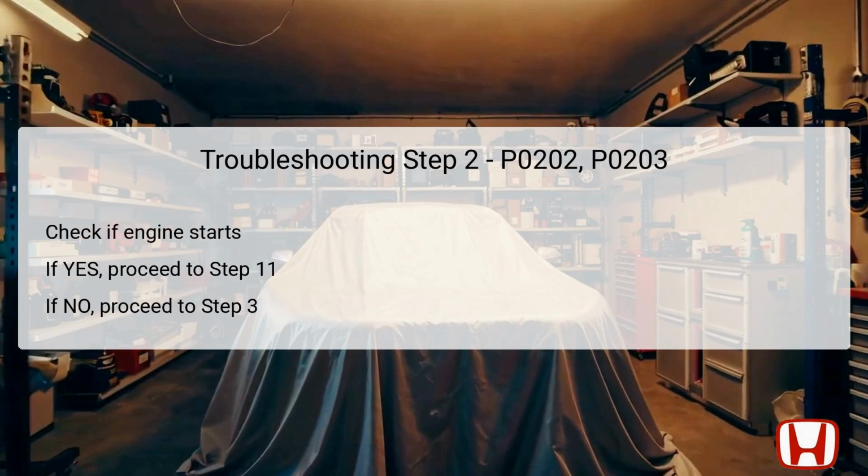After attempting to start the engine, assess whether it successfully starts up. If the engine does start, this indicates the potential for error codes related to intermittent issues. In this case, proceed to step 11 of the troubleshooting guide.